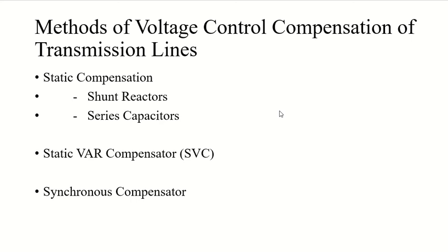So the transmission lines have to transfer power with the voltage drop less than 10%, right. Most of the loads connected to the system will absorb lagging power, lagging VARs to be precise, and the flow of reactive power in a transmission line will cause some voltage drop. It will also increase your I square R losses, right?